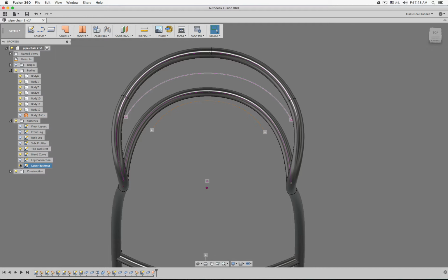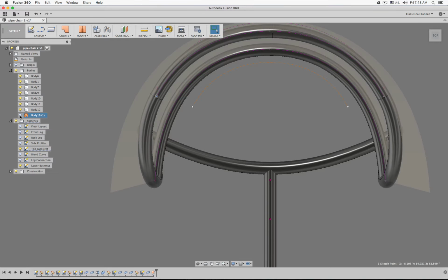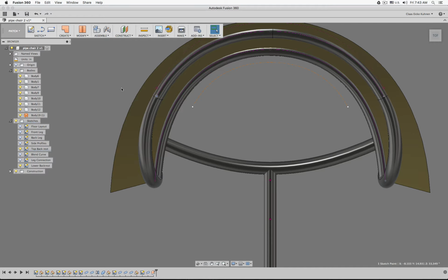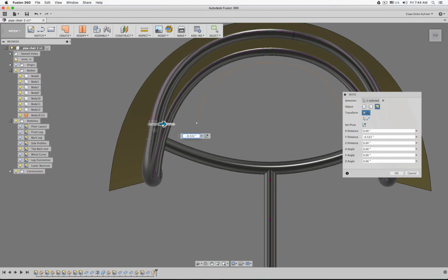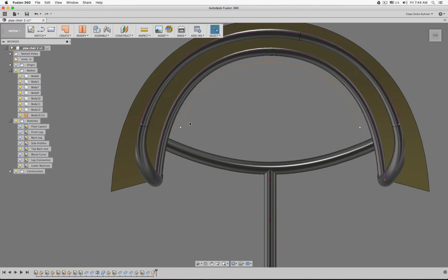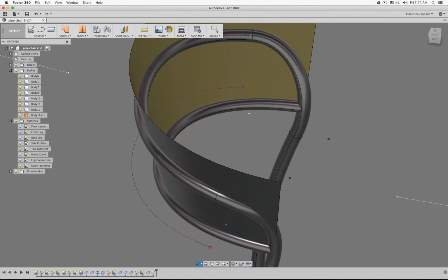So where is my blend curve? There's my blend curve. I made this into an individual sketch, so I can simply select the point of my top rest, and now, seeing the surface, I press M, and for example I can move it down, bring it back to there, and try to see where it intersects the surface. There, click OK. Good. Okay, a little bit better.